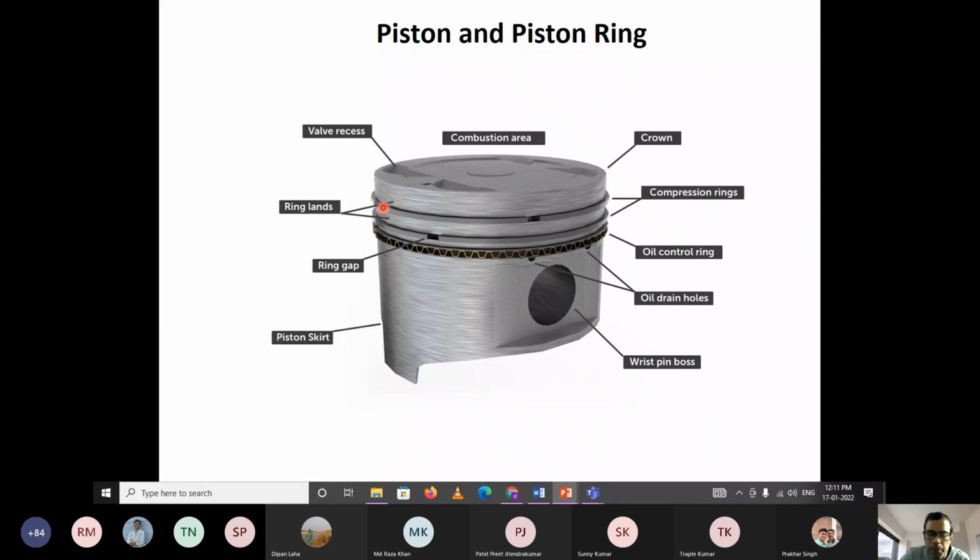There is only a possibility of slight physical contact when the piston has its reversal of direction, either at the top dead center or at the bottom dead center. After that there is no physical contact between the ring and the liner. There is a very small lube oil thickness, probably in the order of micrometers, that separates them.